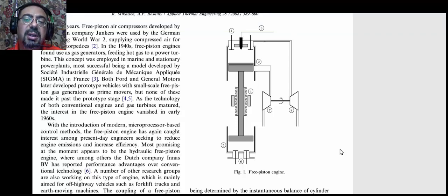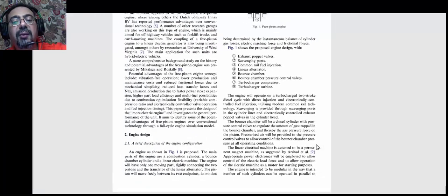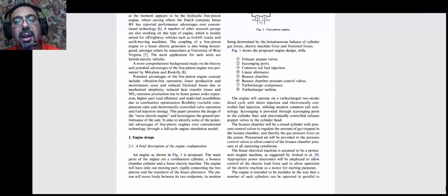Okay, so of course again efficiency is really hard, and that's why they have all those innovative designs. In that design, that's a free piston engine. There's no crankshaft, the piston is just going up and down, and there's an electric generator over here, and it uses the exhaust, which is very hot, to run the turbine, which is running the compressor that does the compression for the engine, but you also get a power stroke in that engine. So there are all these ideas to improve the efficiency, and hopefully in the future we will see something like this in every house.